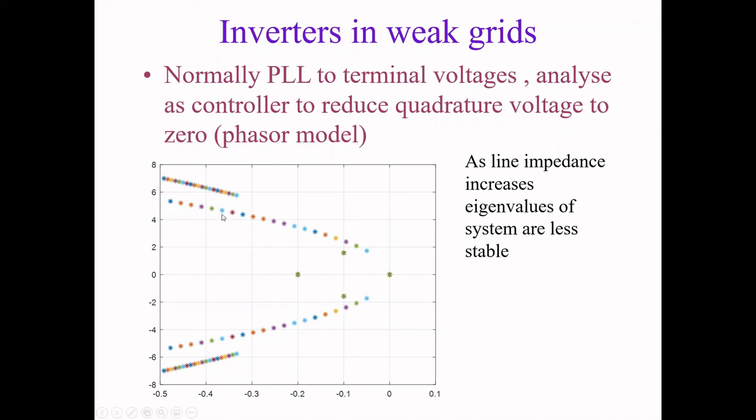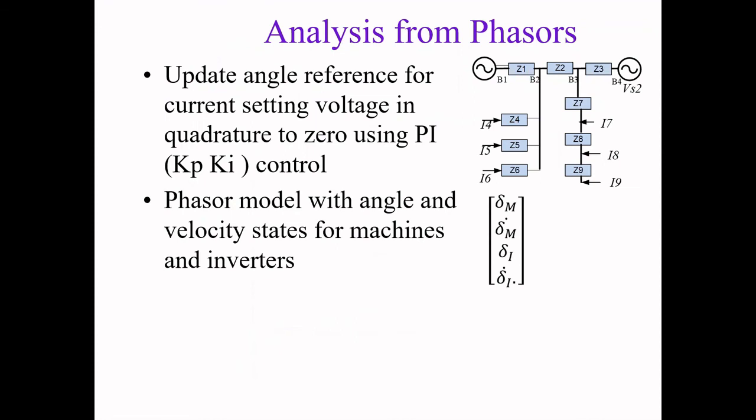But when we did this analysis, we find that these eigenvalues migrate to the right. And if you're not too far from your history of stability in continuous time domain, you say eigenvalues heading to the right, bad idea, introduces instability. And that's a characterization of what actually was observed in the real system.